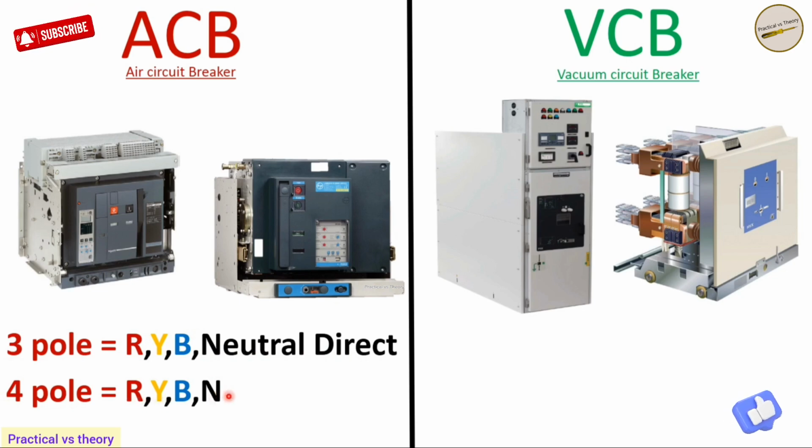In this, the neutral is not direct. In this, the neutral is already connected to the ACB, okay? So, if the ACB is switched on, the neutral will also turn on and off along with it, okay? So, there's no direct neutral in this. So, you get a 3-pole ACB and a 4-pole ACB, okay?